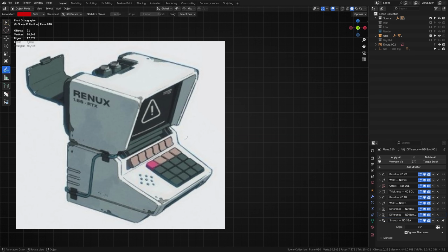The screen hood is a good detail. We must apply several different principles to break it down. The first thing we should look for is a plane that cuts through it, giving us a mirrorable surface. After looking at it for a moment, the only surface that works is running right through the center from the back of the hood to the front. If we look at the back, an extrusion operation alone wouldn't quite cut it, as we have a cutout detail that interrupts the guiding edge.